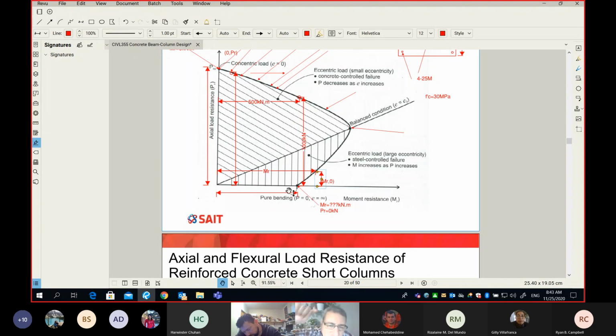I know this is a long shot, and it has been a few months, but I'm going to remind you. If I'm designing a beam, forget about the column for now, please. In beam design, I told you that we need to make it a tension failure where the rebar yields first. And remember, the rebar was in tension, so it will yield under tension.